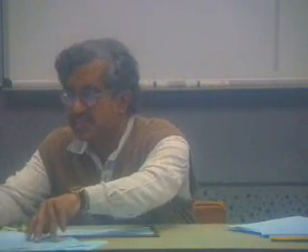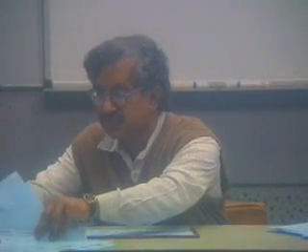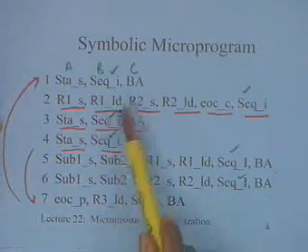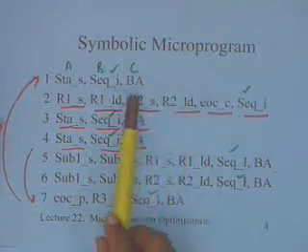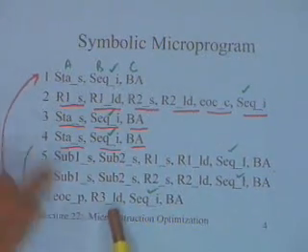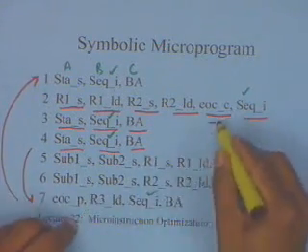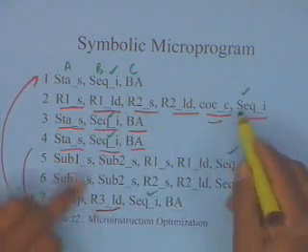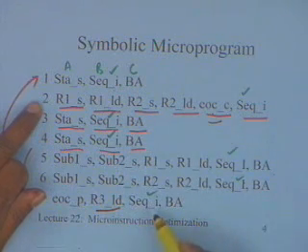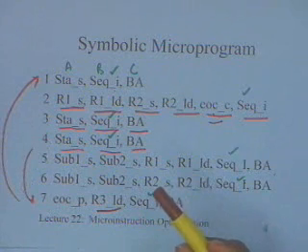Basically, the implication is, let us say, initially you have a horizontal microprogram, and if you have two columns which are disjoint and you define one column, then wherever either of them appears, you have to say that it is appearing. So let us say R3 load is disjoint with EOC. If I take these two columns and initially make it one column, then wherever this appears or wherever this appears, all the control signals with which this appears, there will be no edge. So that will be reducing your merger graph. The possibilities of combining will get reduced because multiple control signals are present in the same field.